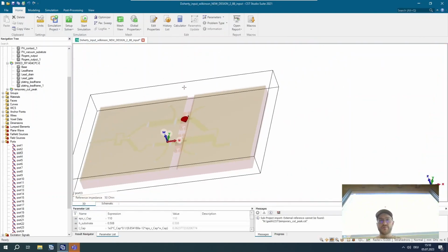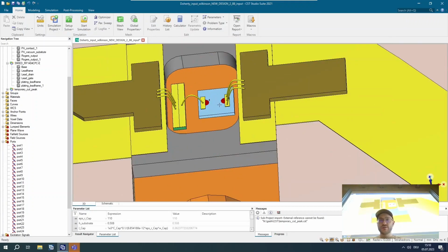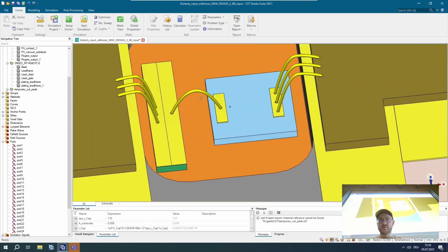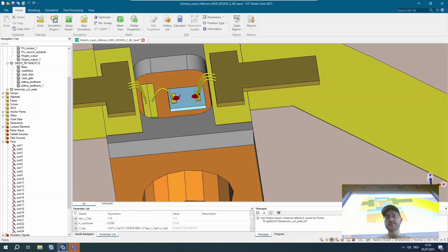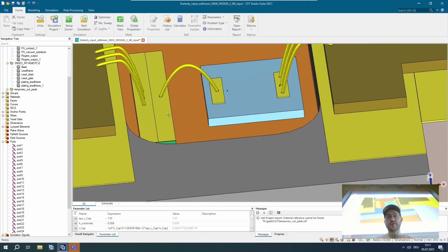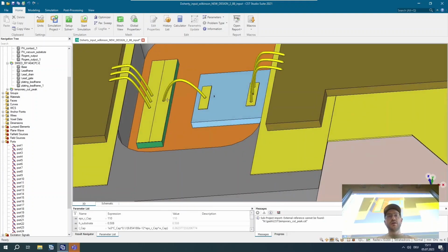So we have this representation of the transistor bar, where you have a lot of fingers here, and we can see there's bond wires that connect. And this is with respect to, as we said, the input matching: whatever the input matching is, it is not the input matching that is required for your device. Thus, you have an LC network in this case. The L is taken from the inductance of the bond wires, and the C is taken from this metal insulator metal capacitor. So basically, there's a metal on top, insulator in the middle, and metal downwards. And this LC network is used to transform the input impedance to a target which you would like to see.